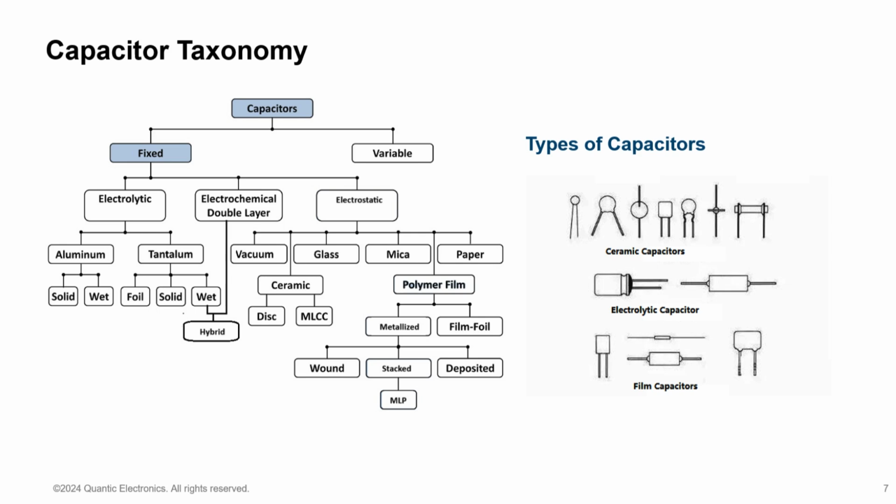The electrolyte can be an aqueous liquid or a solid conductive material like pressed carbon or more commonly today, conductive polymers. The construction allows for high cap density, but the need for interaction of polarized molecules in that electrolyte solution increases the internal impedances and lowers the frequency response capabilities of the electrolytic capacitor technology.